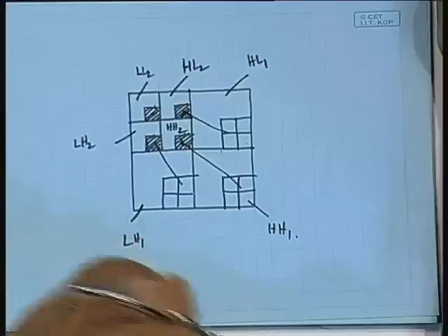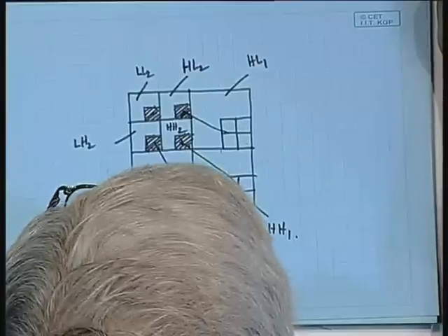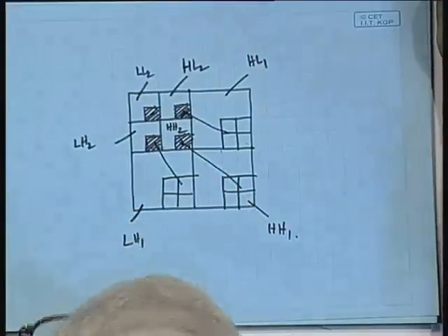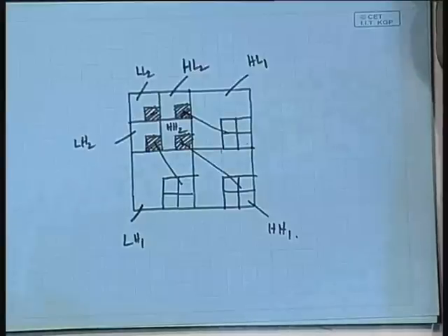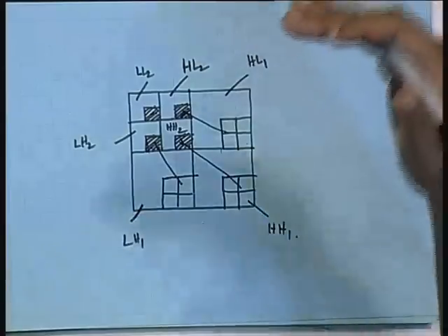If I draw it with 3 levels of decomposition, 1 pixel in HL3 would correspond to 4 pixels in HL2, and every 1 pixel in HL2 will correspond to 4 pixels in HL1. Which means 1 pixel in HL3 would correspond to 16 pixels in HL1. So there is a tree that evolves.